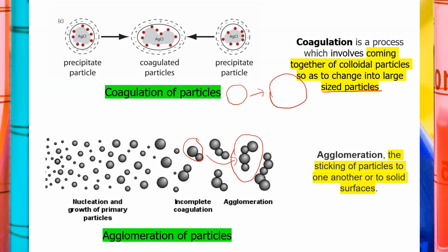So if you combine the nucleation mechanism with the digestion process, it starts with the nucleation process to form a product, and then the product starts to coagulate to form a large particle of product, and then the agglomeration takes over to form the crystal. So I can say that the crystal product starts from the nucleation mechanism, goes into the coagulation process, and the last one is the agglomeration process to form the crystal of product.